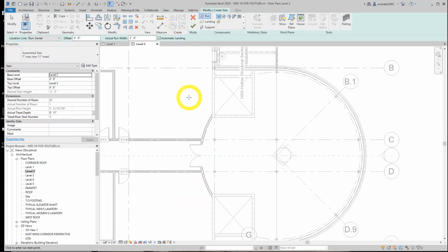So let's look at our options. Stair command has a different workflow to it. There's a few little steps. You generally make your boundaries and your runs first, and there's some different settings than we're used to seeing. So we're essentially in sketch mode right now, as you can see by the finish item mode and cancel. And these are going to get pretty typical. We got our run and landing and boundary. We're going to see a different few options as we go through this, depending on what we pick.